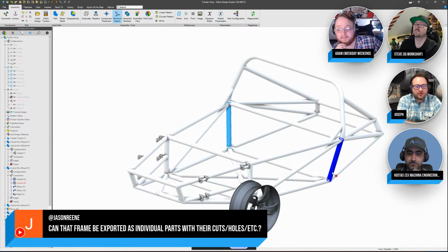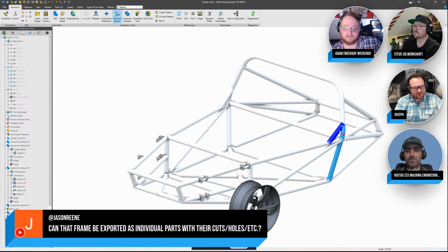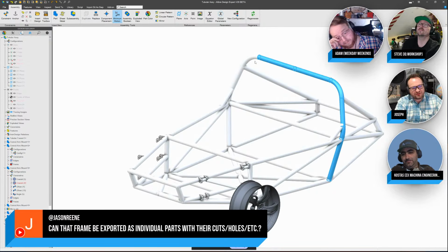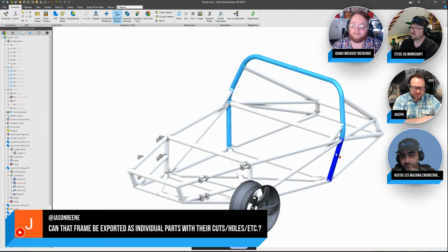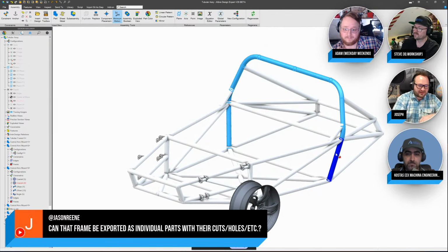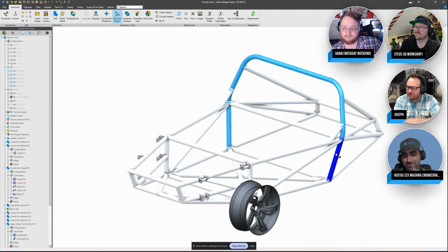That is going to be a driven part. So when we export this, if we want to make changes to it, we make changes in the Weldment file and the part updates. But if you put features on the driven part itself, I don't think those are going to be updated in the Weldment. So just make your changes in the Weldment, and then you can export that promoted part for drawings, and the update is kind of in one direction. So I think that will probably be the only caveat that we see with that. I think it's a really small deal.